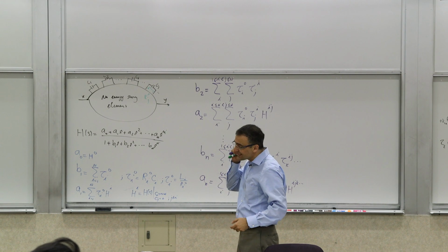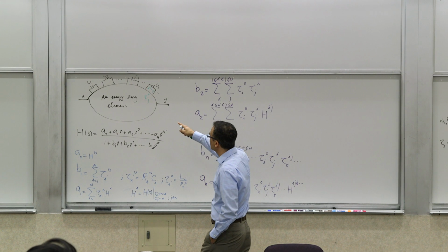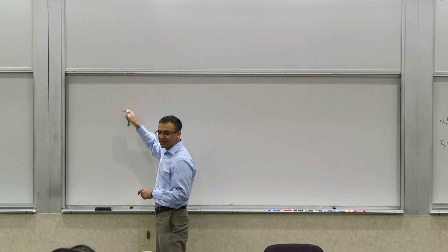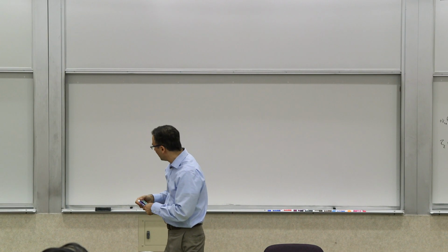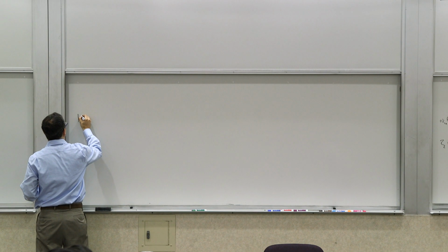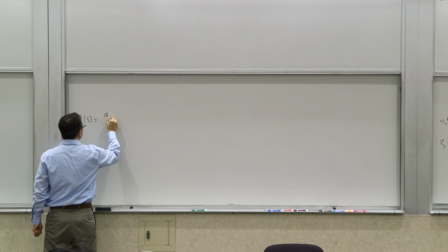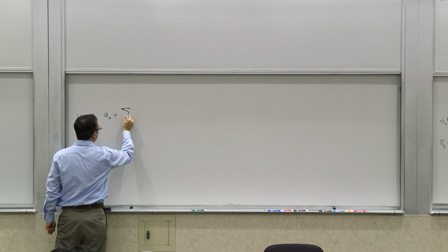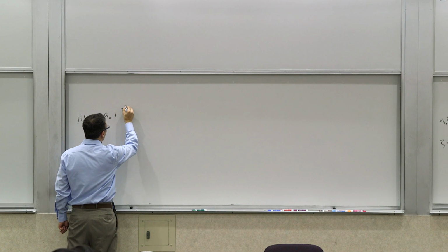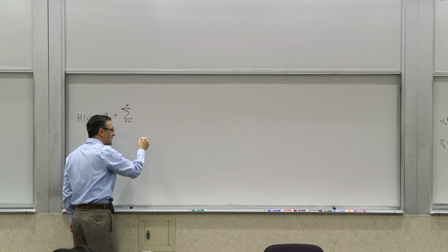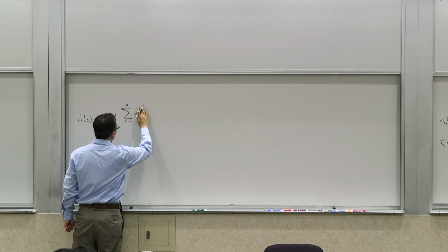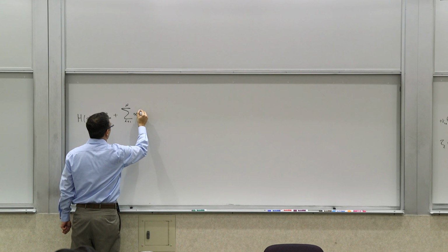So in this setting, you remember when we said we have something like this, we could write the transfer function, and we did this before. We can write it in the following form. You can write this transfer function as H(s) equals a0 plus, and then we did this when we did the derivation, for example, of the zero value time constant calculations, the sum for i equals 1 to n. We wrote it as alpha 1i.